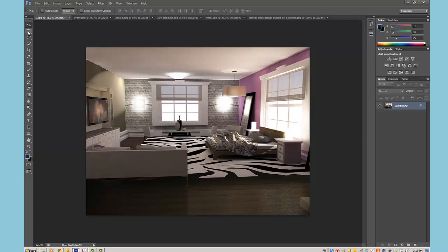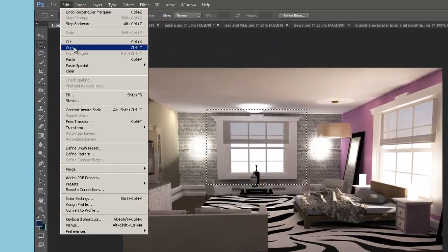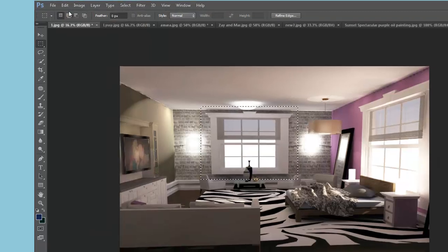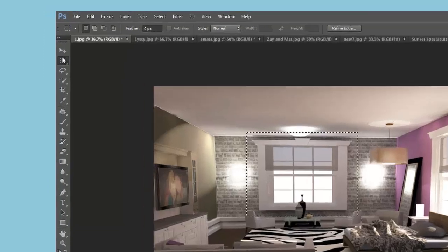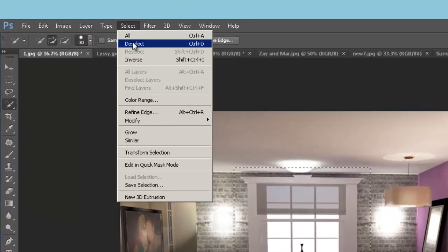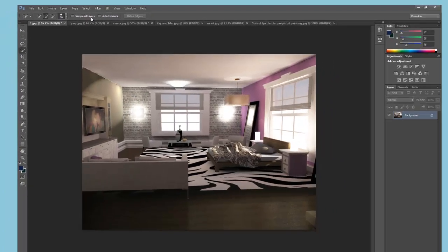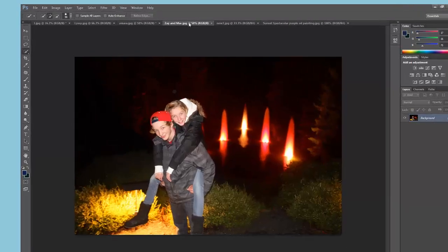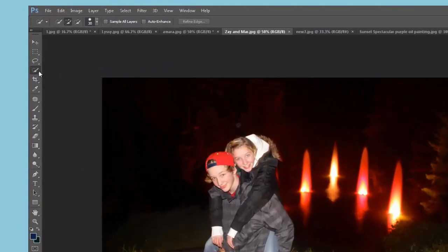Next, we'll learn how to use various select tools in order to cut and paste elements, people, or accessories into our interior space. The first one you will see on the top left-hand side of your screen is the Rectangle Select tool. If you click and hold on this icon, you will see other options such as the Circle Select tool. Click and drag an area onto your screen. Under the Edit menu, choose Cut. It's easy to cut sections out of our drawing in Photoshop.